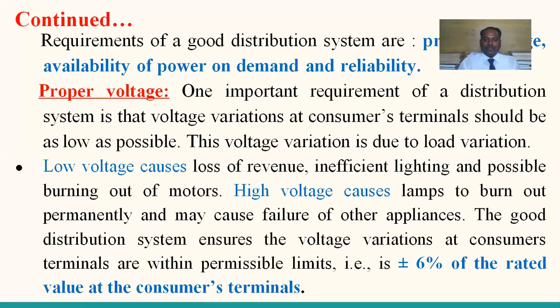But what is your feeling? So what is the importance of voltage? Voltage variation or voltage fluctuation can damage our load appliances too much. This is not at all acceptable. It is the responsibility of the utility as well as the consumer to keep stabilizers and so on, so that you are protecting the load equipment. As per the IEEE standards, hardly plus or minus 6% of the rated value at the consumer terminals is acceptable. Beyond that, there is no possibility for the voltage variation. So therefore, the design and requirements of a distribution system, along with the physical and technical parameters, play a crucial role.